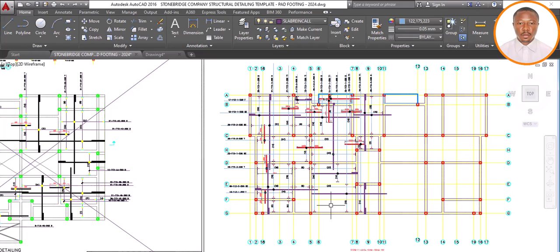It will label it as beam 6, but in a real sense what you have is 5 beams, because you deleted one and replaced it. Likewise, if you also delete one, maybe beam 8, and put another one, it is named beam 9. But in a real sense, the total beams you have might be 6, yet because you don't know how to solve that problem, it might be showing you 8 beams.